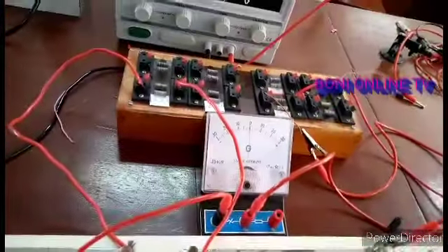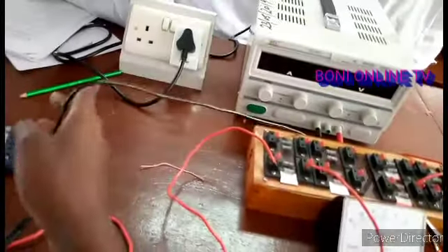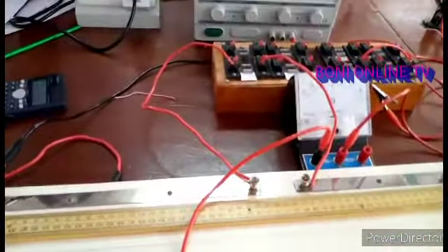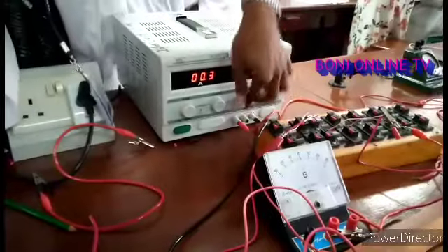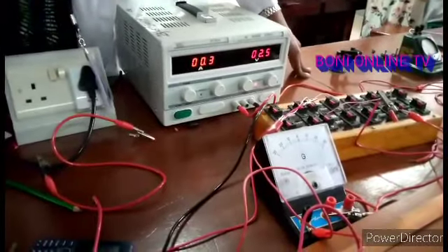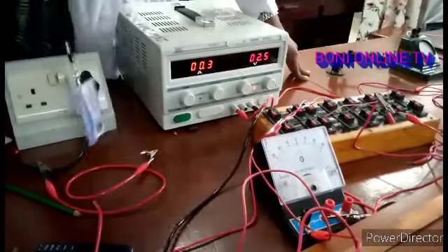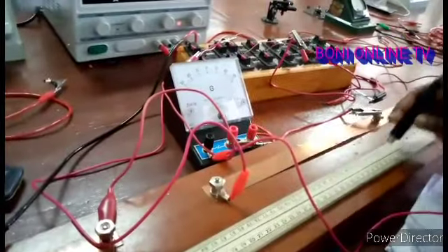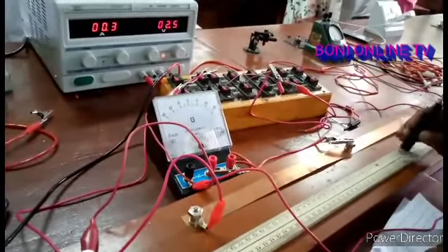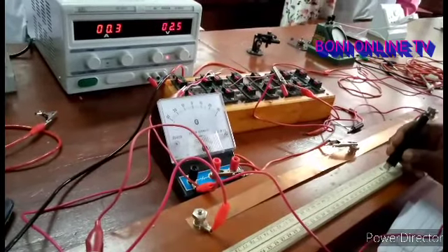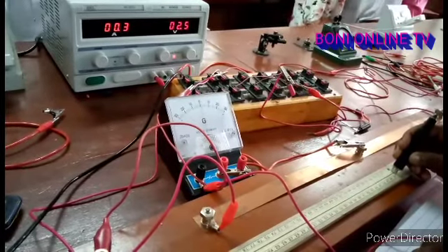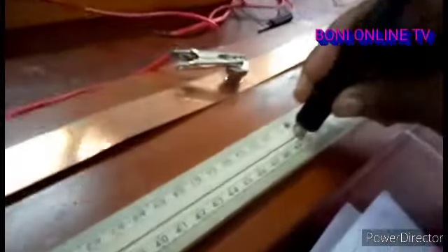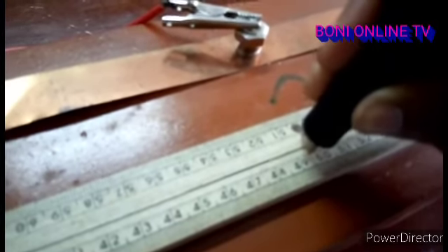Thereafter, I'm looking at this wire to the galvanometer and another wire from the power supply. Let me see how to start this experiment. The first data I take is when the power supply connection is normal, that means the positive of the power supply to the positive of the circuit, and the negative to the negative. Now I reverse that: the positive of the power supply to the negative of the circuit, and the negative to the positive of the circuit. Then I find the balancing point of the galvanometer.